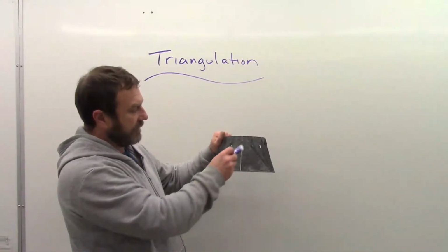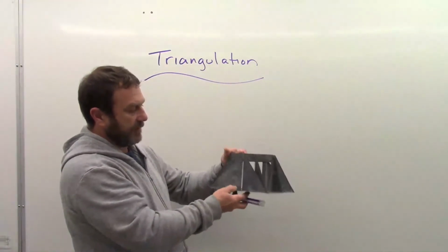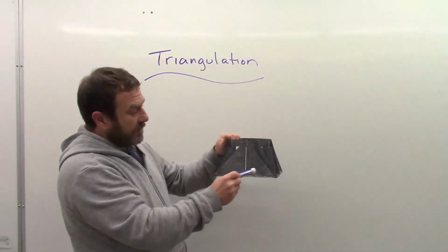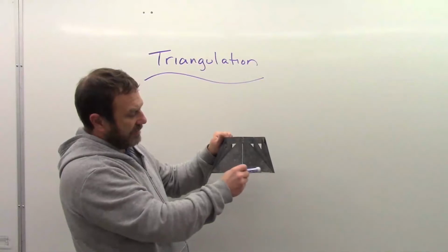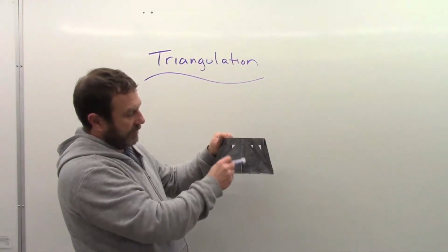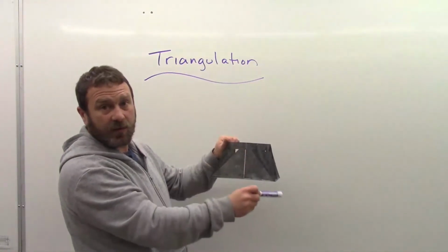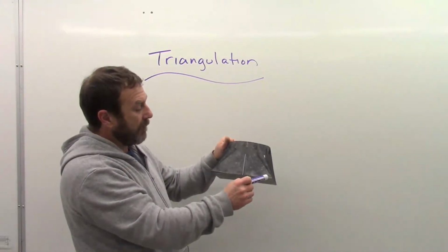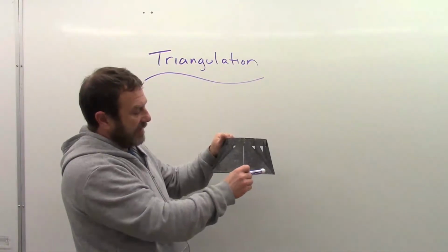Again, look at just the side view, or when we look at the three-dimensional view of it. When we look at these triangles, we can see that we have the base and the height. And you put those two at 90 degrees and we gain the hypotenuse, which is what we call the true length, the element line.